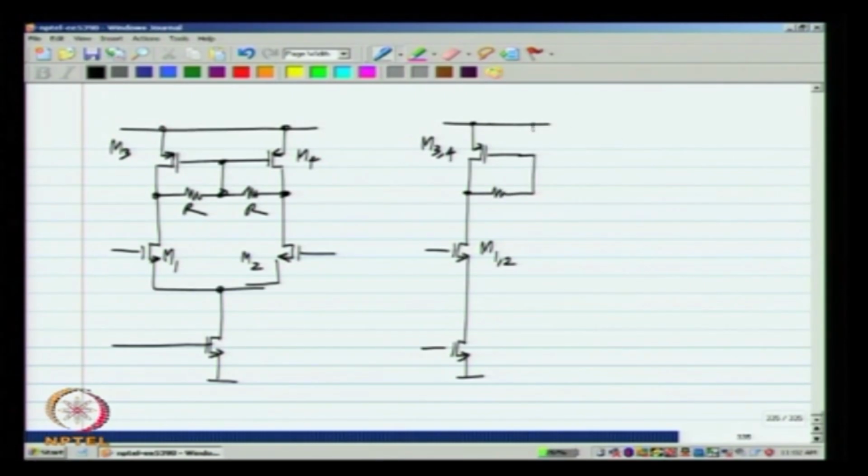okay. So, there may be some parasitic capacitance here, I will call it CP3, and then to make this into an op amp we will have the integrating capacitors C. Okay, we will have that.